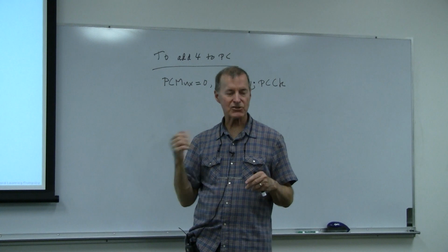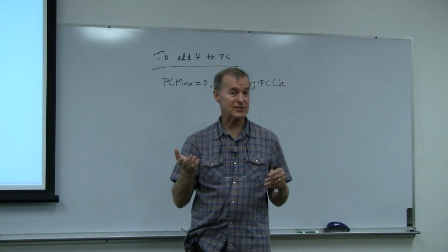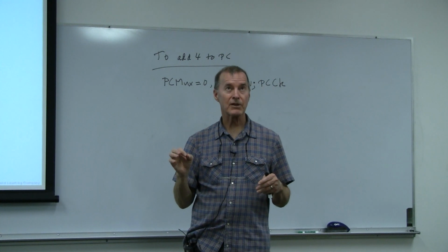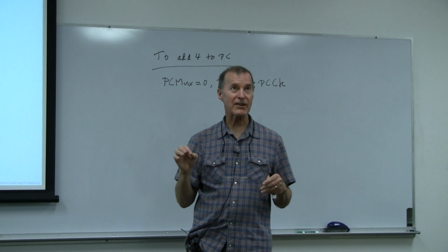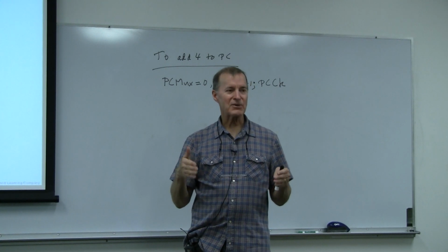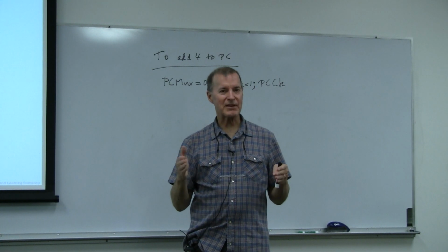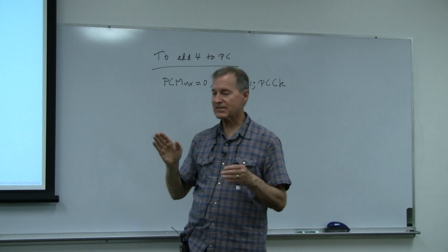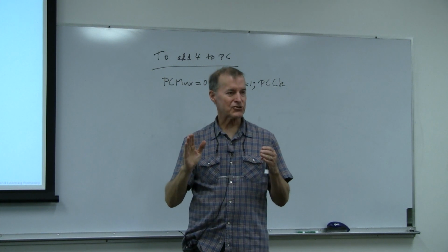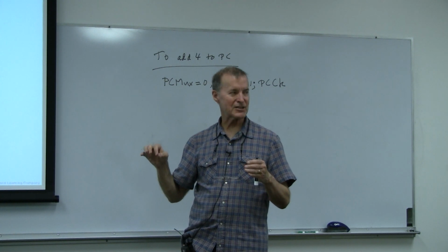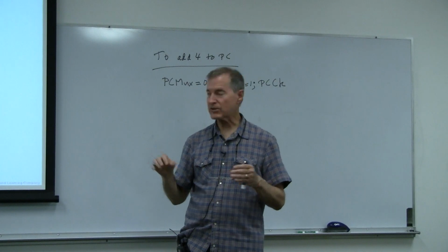So therefore the last 2 bits are missing. The 2 least significant address lines are missing because each instruction is always going to be at an address that's aligned by 4. So consequently, a 26-bit unsigned integer in an instruction is assumed to have 2 trailing zeros in that address field.